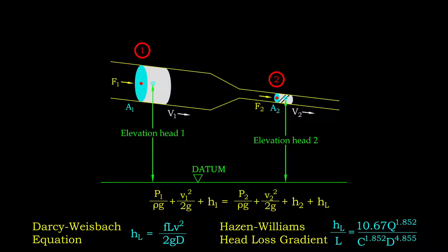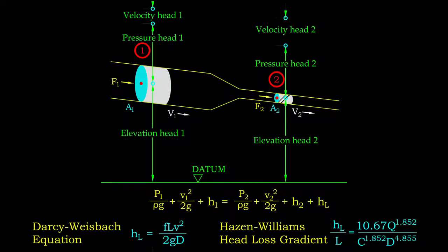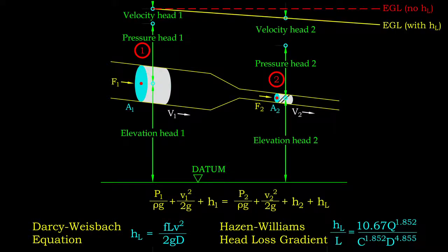By adding the pressure head, velocity head, and elevation head at one point, we can determine its total energy. When we do this for all the points along a pipeline, we obtain an energy grade line, EGL. The difference between the energy of 2 points is the head loss. The head loss with respect to upstream or the source of fluid such as reservoir is usually of concern.